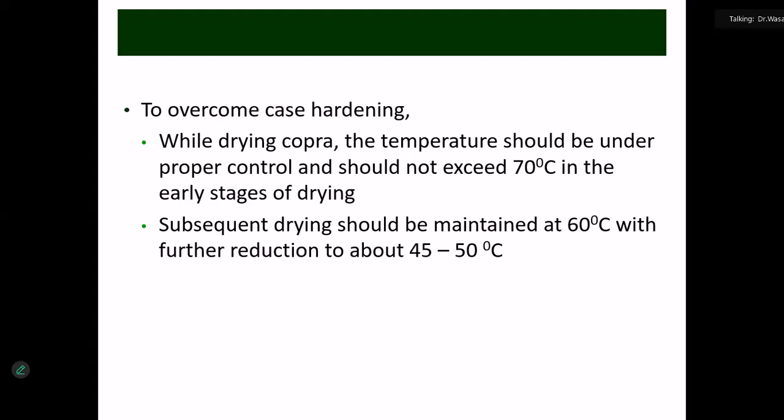Normally, sunshine and smoke drying should not cause this. It especially happens in hot air dryers. Sunshine never causes case hardening. Sometimes with smoking, if you use too much fire, it will happen. So the maximum temperature during the initial stage should be 70. Gradually reduce to 60 and at last 45 to 50.